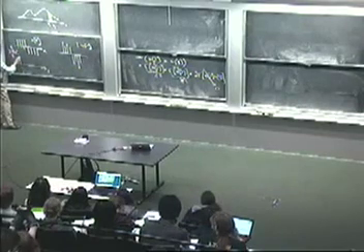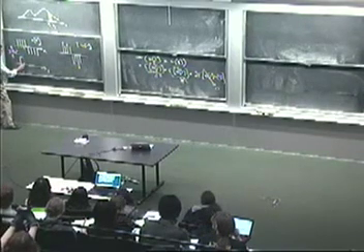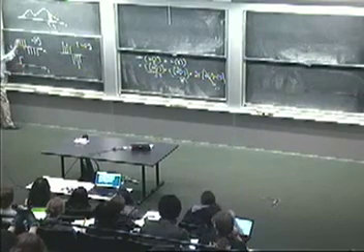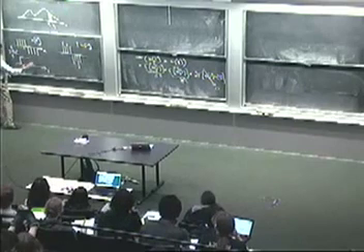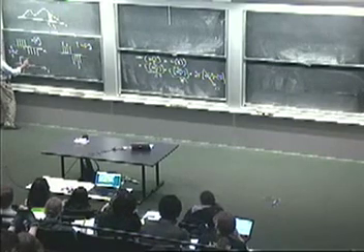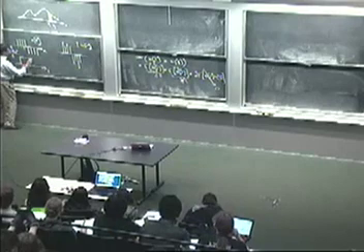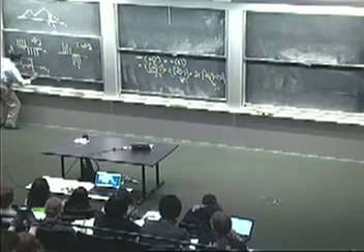So you take the value here, hold it for some interval of time, T seconds, then you take the next value, you hold it for T seconds, and so on. And then when you get a change in value, you change to the new value. So you would hold this here and then come down here, hold it.